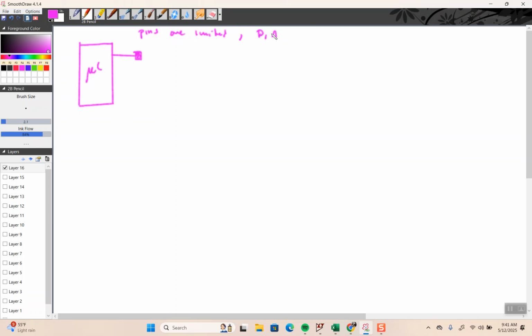Digital to analog converters on a chip take area, right? So what you can do is have a pulse width modulated signal, right? That's going to give me a half, right? It's going to give me like a quarter. And that's going to give me 3/4.